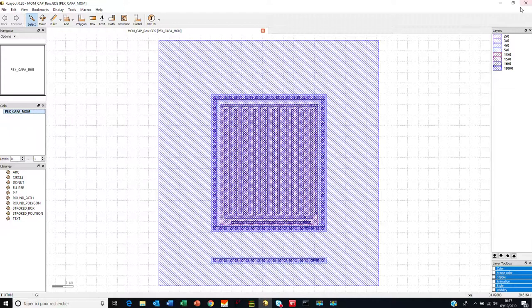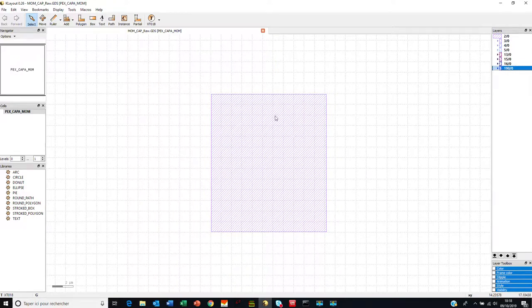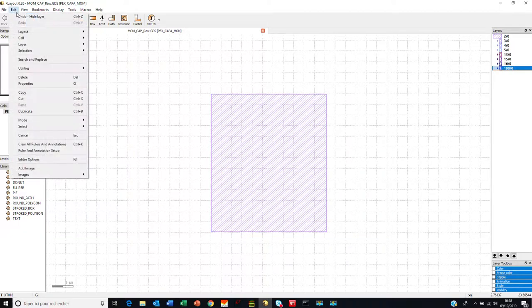When we look at the data from the layer map table, we learn that layer 2 is the NWell layer. We will hide everything but the NWell. The concern is that the PWell, which is defined where no NWell exists, does not exist in the GDS, so it has to be generated. But before generating it, we need to define the PWell layer. This is easy to do.